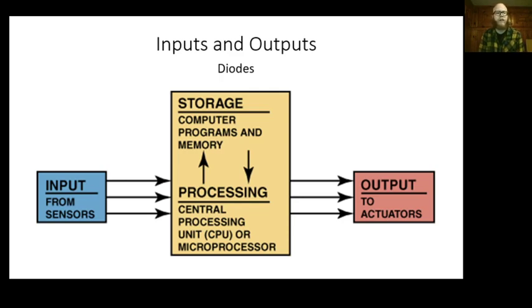In this case, let's call it a body control module that's monitoring this. Okay, I don't really care that I'm at 3 miles per hour right now. At 5 miles per hour, all of a sudden it gets excited, and it looks to see if the doors are locked, and if they aren't, it locks the doors. After 5 miles an hour, at 6, all of a sudden it doesn't care anymore. At this point, the vehicle's moving down the road. We've passed that threshold at which the car should have locked the doors all by itself. And so now it can spend its little computer time focusing on other things.